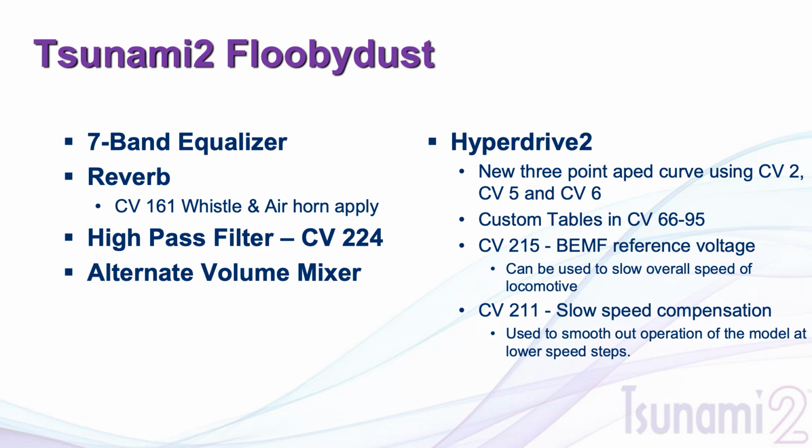And so these low frequencies that a speaker physically can't do, you can filter that out with the 7-band equalizer. But you can also boost the low frequencies that it can reproduce. So in the case of our Minicube speaker, which is capable of down to 100 hertz, you can really boost that mid-range and low range to get the most out of that sound.